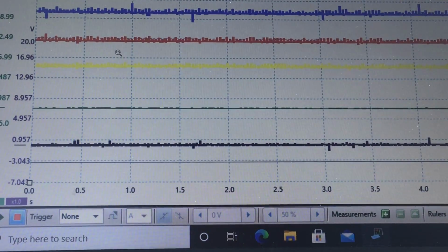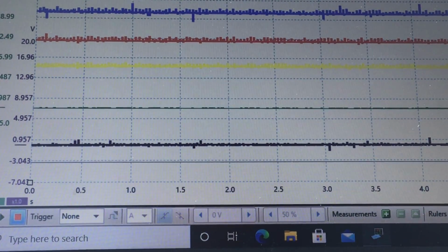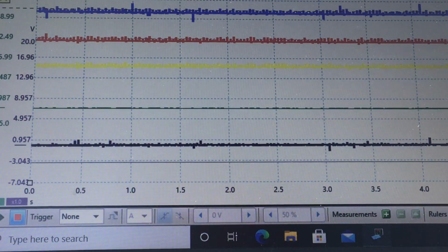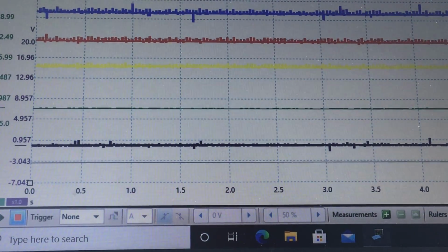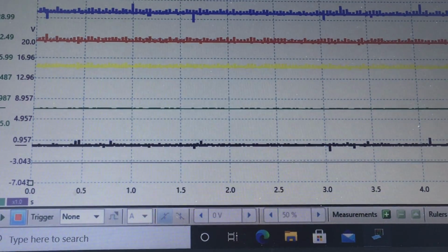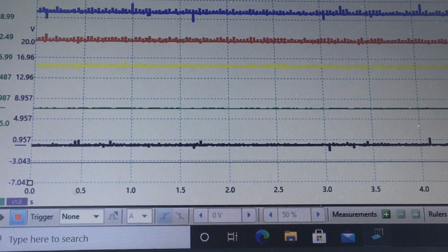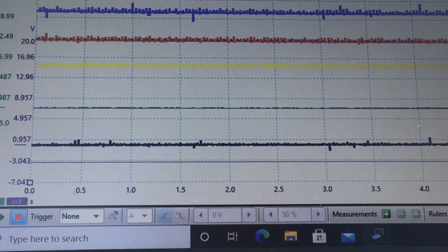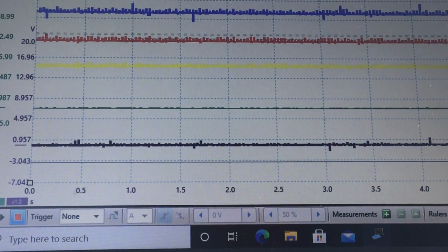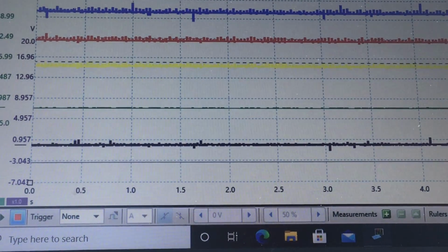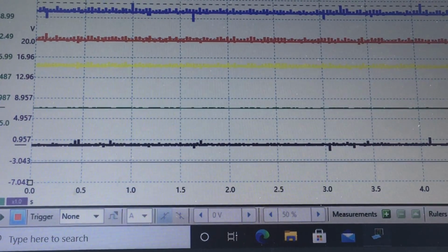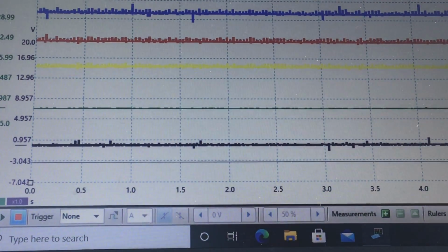Okay, this is when the blower motor was not on, when the car was running. Here we go. We got voltage. We got charging voltage at the blower motor on the blue channel. Let's look at the red channel and see what we got there. We have charging voltage there. Same thing. Our yellow channel is our feedback, which is probably going to be about charging voltage, because you can look on your schematic, look at the feedback circuit.